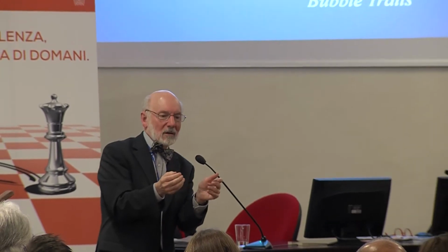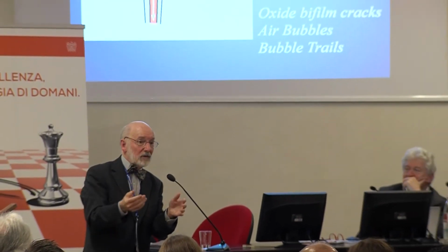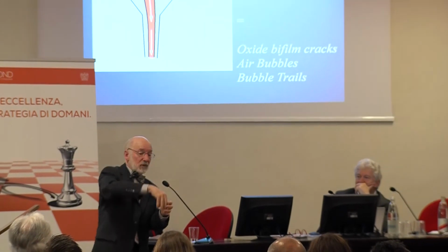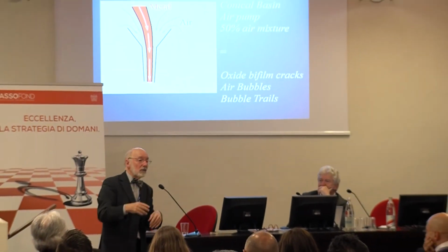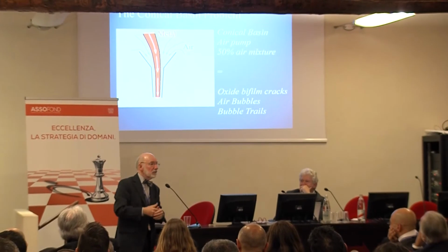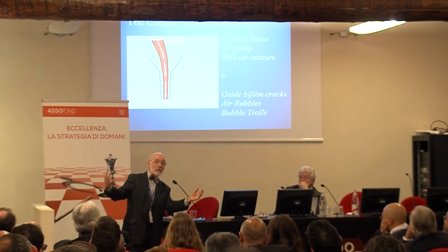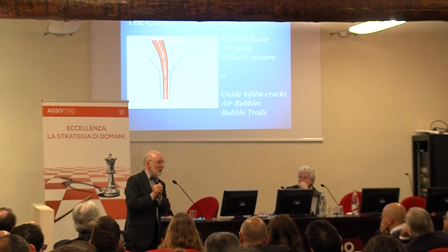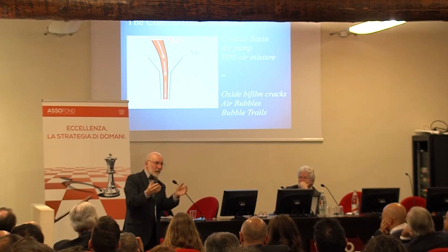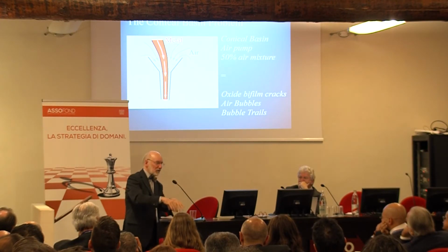The real problem is the cone that leads into the running system. And we all pour down a cone. Everybody in the world uses this. But if I draw a cone to my chemical engineering friends, and I say, what have I drawn? Now I'm putting a fluid down the middle and I've got a cone. Oh, they say, it's obvious. It's a pump. And it's a pump for pumping air. Okay? So the cone takes in huge quantities of air.